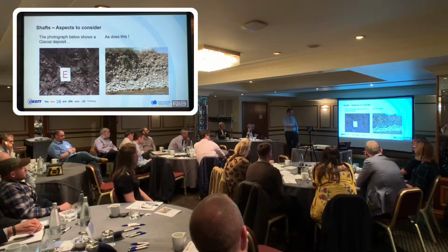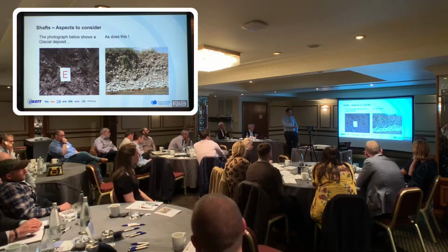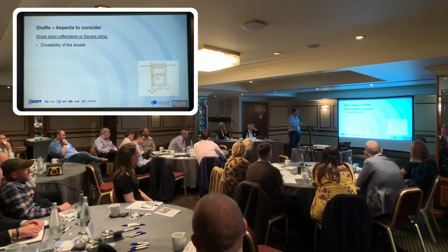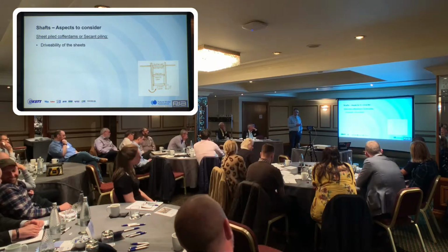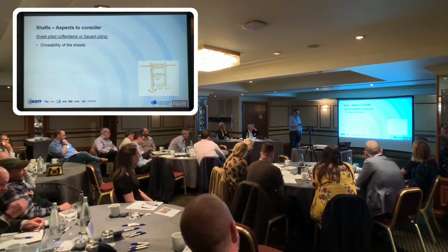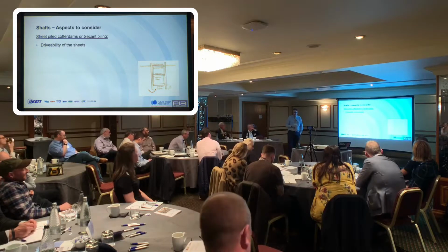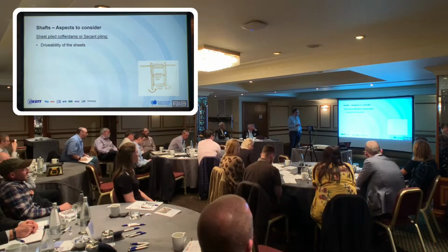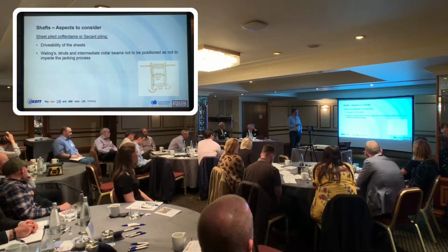And certainly, if you get some of these boulders under the cutting edge, you'd be struggling. So just briefly on the sheet piled cofferdam, you need to consider drivability of the sheets for the ground that you're in. Again, if you think about that slide I've just had up there, trying to drive sheets through cobbles like that, it's probably not going to be a clever thing to do.